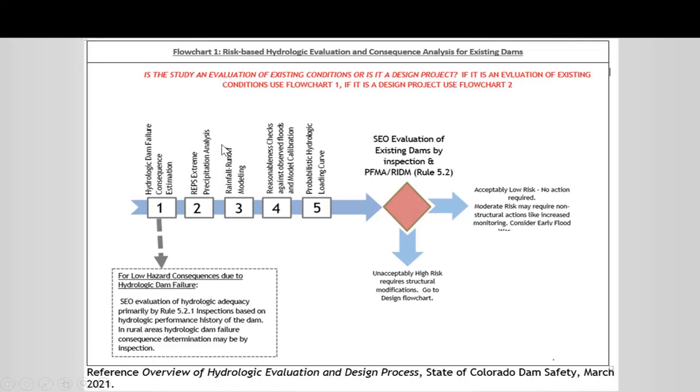Remember, there's 7 AEPs, annual exceedance probabilities, 1 in 10 up through 1 in 10 million, and then there are 3 different storm types. So we have the 2-hour local storm, the small intense thunderstorms, 6-hour MECs, medium size, medium intensity, and then the long duration, 48-hour low intensity MLCs, or mid-latitude cyclone storms. 3 storm types, 7 AEPs, so that's 21 storms total. Get all those from REPS.